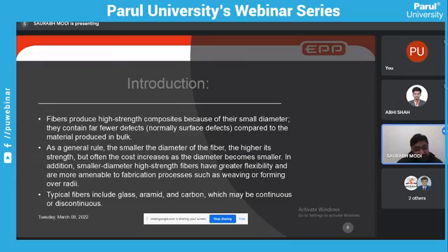A bigger diameter hole is definitely advantageous from a manufacturing point of view. If the diameter of the hole of the die or mold is smaller, then it will create some manufacturing difficulty. And once manufacturing difficulty arises, it will definitely come with some cost. So the same thing is here. We need to manufacture the fiber. If we need to manufacture a smaller diameter fiber, then like I mentioned for metal, the same rule applies over here.